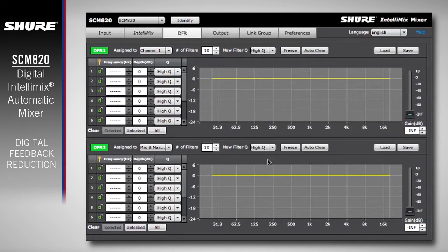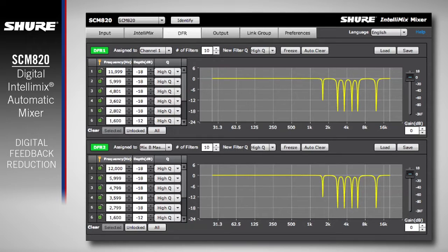A fader for the channel input-output assigned to the DFR function is located conveniently in the DFR window. Adjust the channel's gain here. Use the ring out method to intentionally cause feedback during setup and adjust the filters accordingly. The adaptive notch filters automatically deploy when feedback is introduced. Here we're using sine wave tones over 10 intervals to simulate feedback.